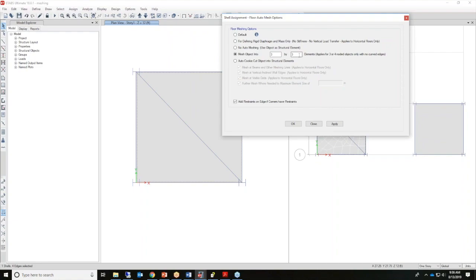I understand that errors with these sometimes aren't easily resolved. It requires perhaps making a much more coarse mesh, because sometimes if the mesh is too dense, it gets really tight, especially in those corners where you have angles less than 90 degrees. I recommend making this maximum element size larger, so you're not getting those tiny triangular mesh element shapes that sometimes cause instabilities.